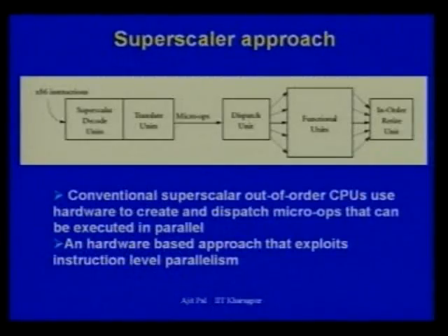So I shall consider a very important example. I don't know whether you are aware of the superscalar approach. Superscalar approach is an approach by which microprocessors are realized. Nowadays, all the microprocessors like Pentium, for example, are based on superscalar approach. Inside the single processor CPU, you have got a number of functional units. Now, to keep the functional units busy, certain additional hardware is required, which is shown here.